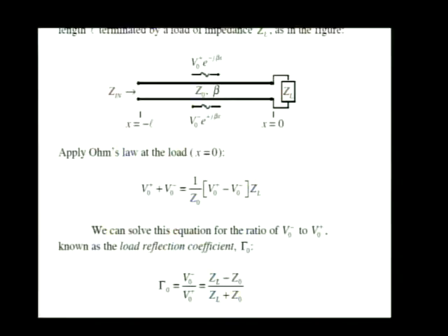Yeah, right. It's called a matched load. A matched load is what would do it for us. That's where ZL is chosen to be equal to Z0. That is, if you've got a 50 ohm line, if Z0 is 50 ohm, the best thing to do, and something we're going to be shooting for a lot in this class, is to match the load to the line. That is, use a load that's 50 ohms also. If the line's a 50 ohm line, use a 50 ohm load.